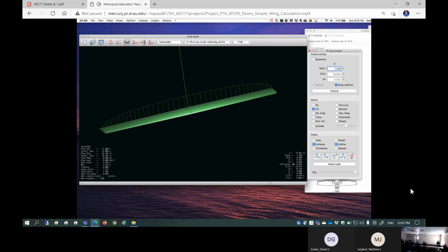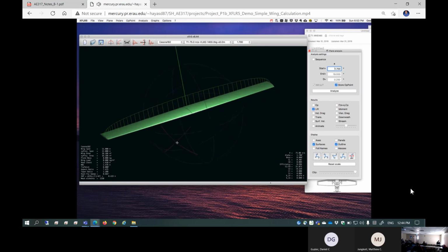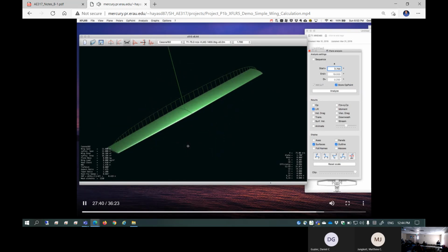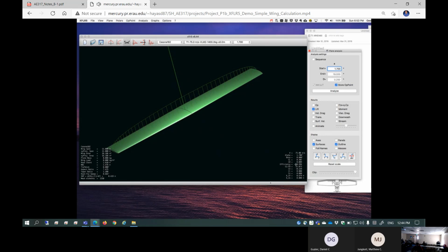Now it automatically reports E for you, 0.996. We could do this by hand. That would just be equal to CL squared divided by the induced drag coefficient times pi times the aspect ratio, and it should report the aspect ratio. Here it is, reporting it right over here. This is all geometry stuff. Anyway, it reports it for you.